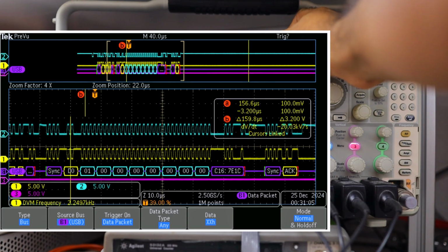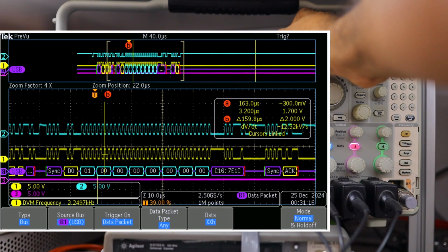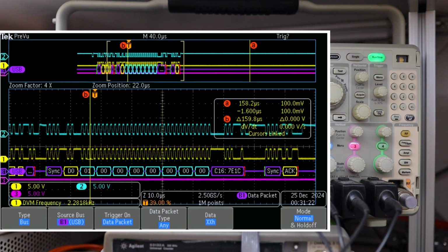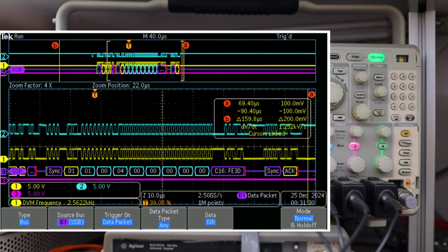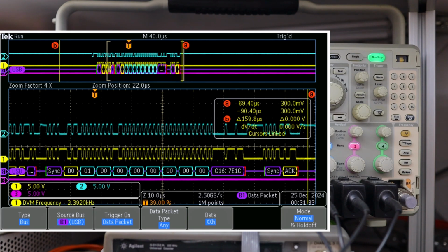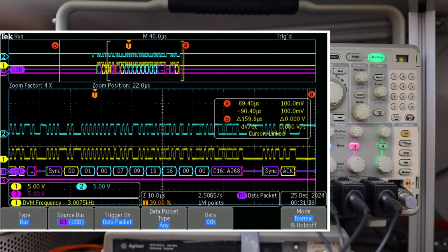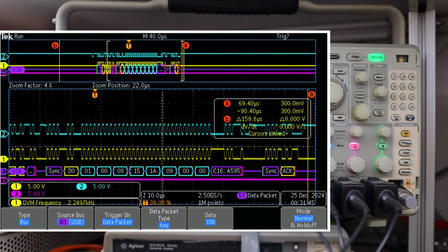These blue bytes you see, 100000, these are the key presses, and if I start to press buttons, you will see this data will change, and of course this CRC16 will also change, and I will let it run so that you can see it better. So now I'm pressing A. You see this data changes a bit, and CRC also changes with it. And if I press a different button, this third byte changes from 16 to 0. And if I press multiple buttons, multiple bytes will change, because this keyboard supports pressing of multiple keys. And I think it supports maybe 6 or 7.